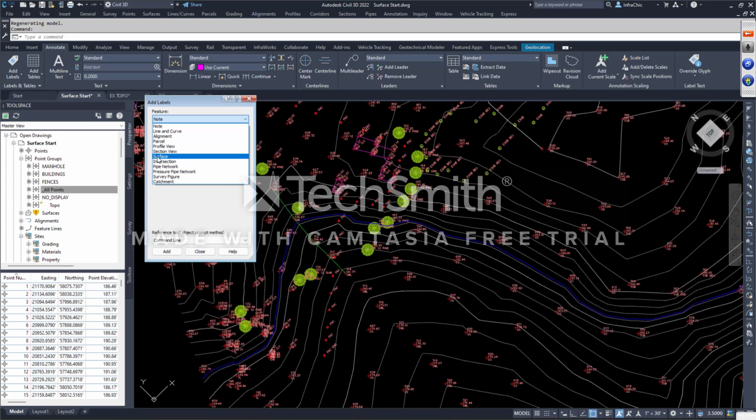If I want to label a surface, I'm going to choose the surface option. Now the type, there are 4 or 5 different types of labels. Independent slopes, that's a slope at a point or a slope between 2 points. Spots, where every place I pick, it labels a spot. Spot on a grid, cut and fill text, that'll ring a bell, cut and fill left to right, up and down, 5 foot apart. Contour individual, one at a time. Contour multiple, a string of contours. One line from bottom to top, every contour in between on that line.